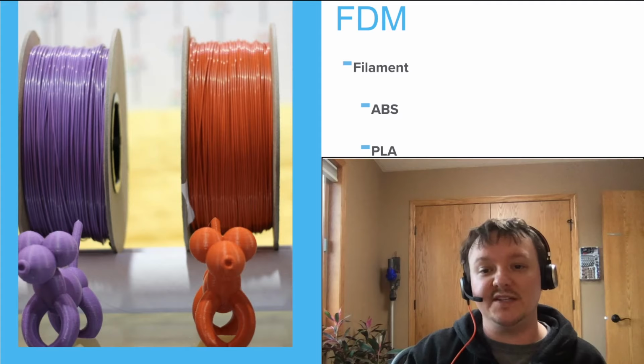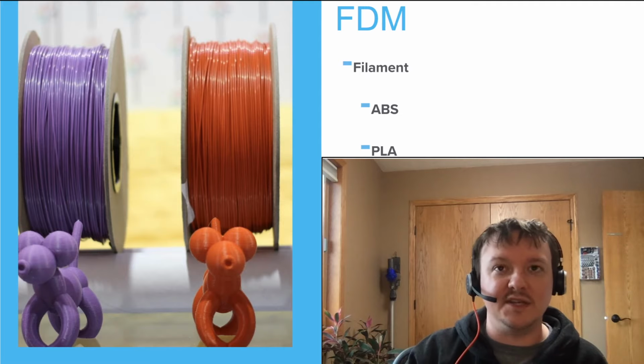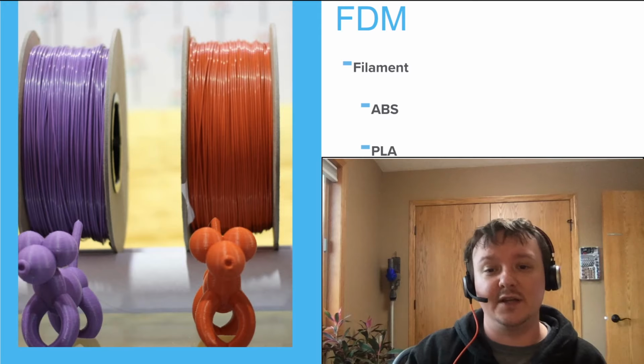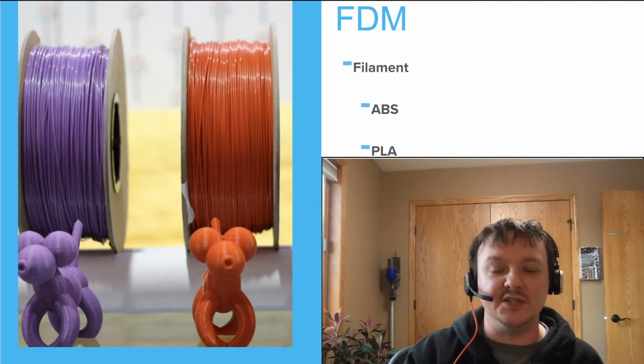The other option is PETG, which kind of straddles PLA and ABS as far as easy to print. PETG is easier than ABS, I find. It has much better physical characteristics. If you're trying to build some sort of a physical part, PETG is usually better for that. It's higher heat resistant.